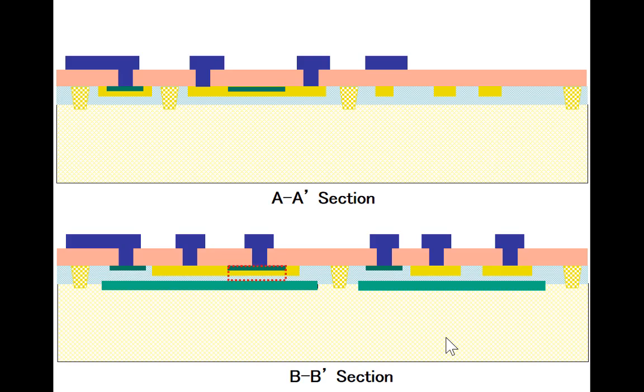So when current flows from the base to the collector, it flows into this, very low resistance, flows laterally here, and then it goes out here. So this buried collector is for the purpose of getting access to the collector from the top without having a lot of collector resistance. Make sense? Okay, so the collector is really right at the bottom of the base region here.